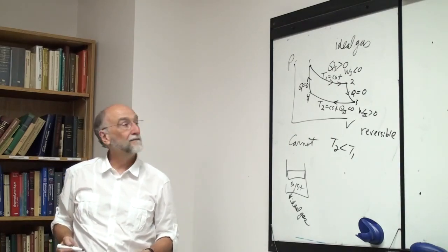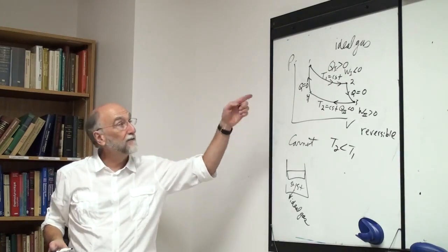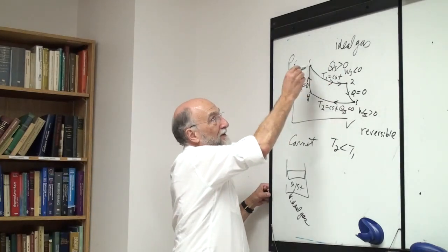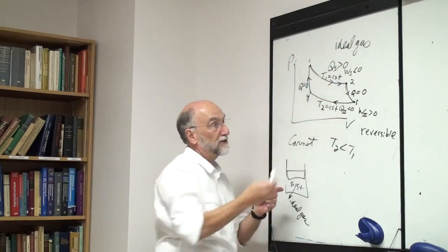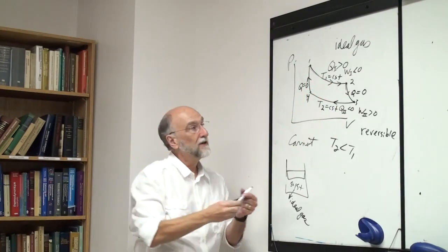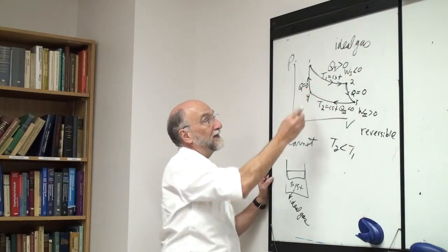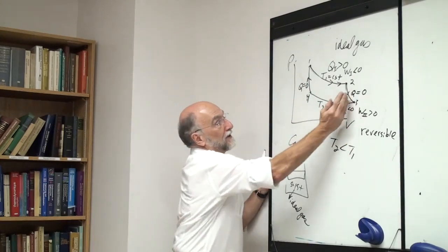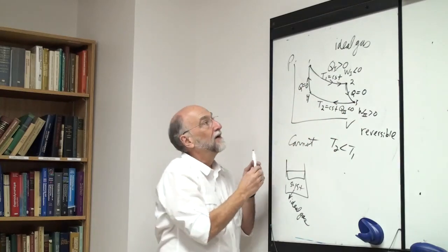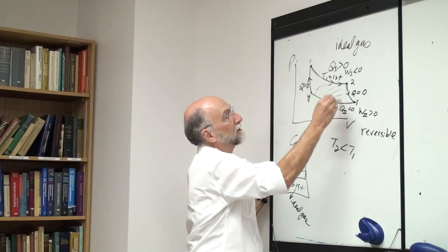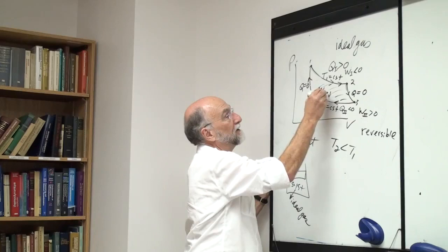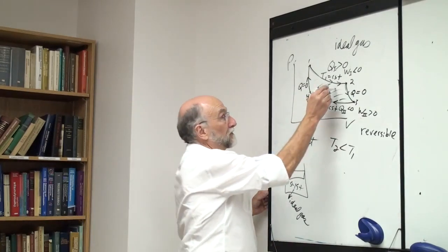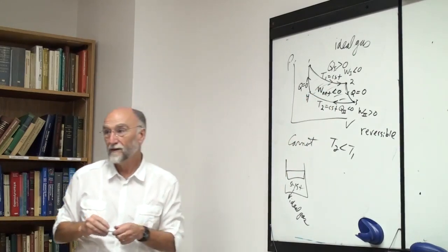All right. Okay, so we're going around a cycle, and after we're done, this is the amount of work that the system did on this stroke. This is the amount of work the system transferred to the surroundings. Here we had to put work back into the system, so the work we had to put back into the system to compress it is equal to this integral under here. And the total work, W net, is the area inside the figure. And that's negative, so the system has done some work. Is that clear then? Okay.